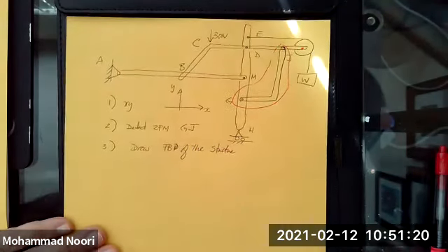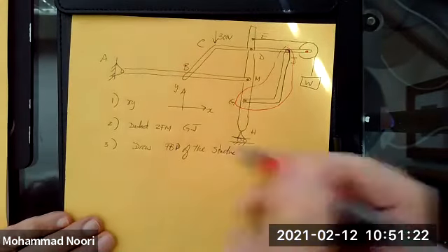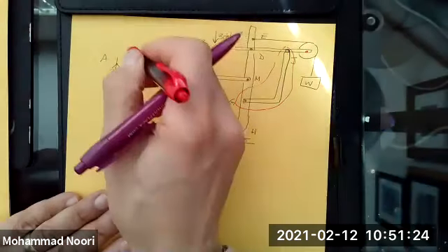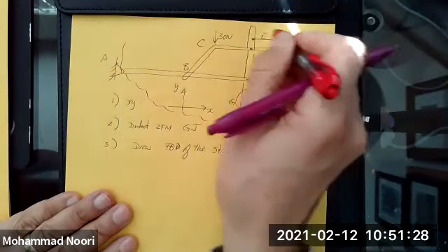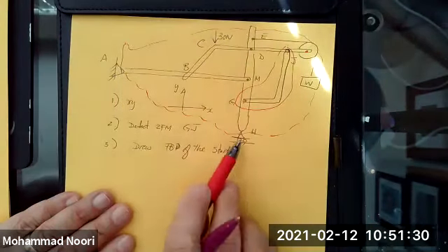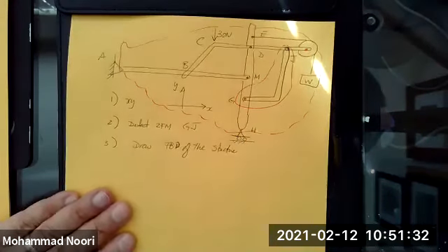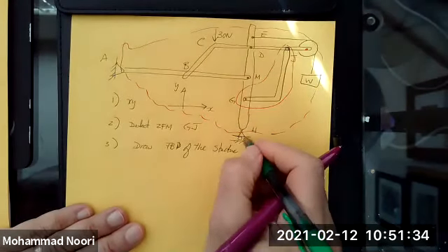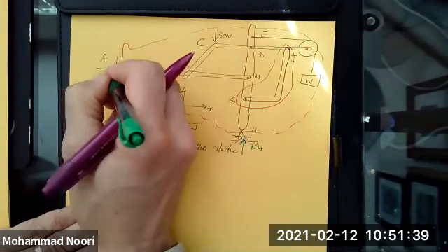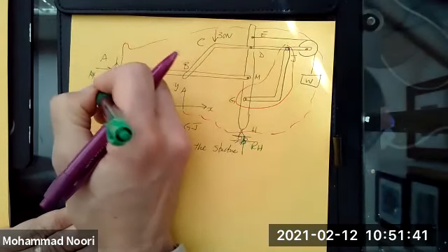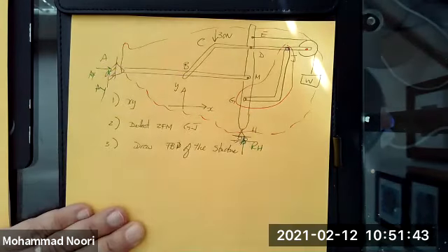Not the pieces, but what you had before. In other words, the structure, as far as you're concerned, is this whole thing that is connected at these two ends. So just draw that free body diagram. This is a roller, RH. This is a pin, AX, AY, right?